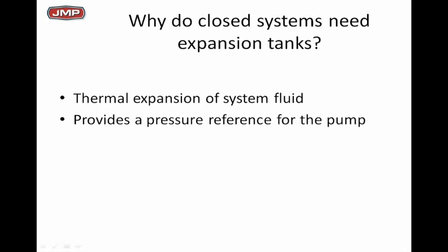Very simple. You heat up water, it's going to grow. You also need a point of no pressure change for the pump. We're going to examine these two things because they're two real good reasons that you need expansion tanks, and you need to understand them when you apply them and when you troubleshoot. Because if you got the wrong size tank, you're going to have problems. And if you don't have it in the right location, you're going to have system pressure problems.